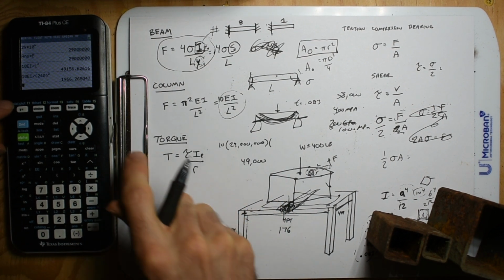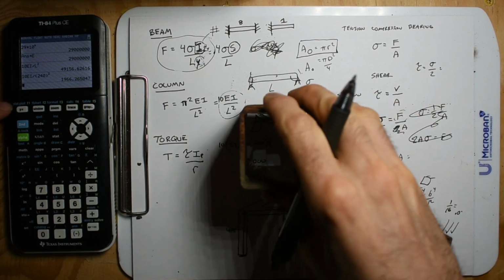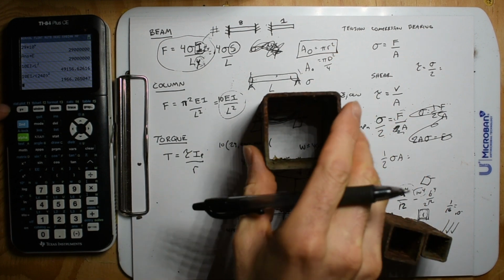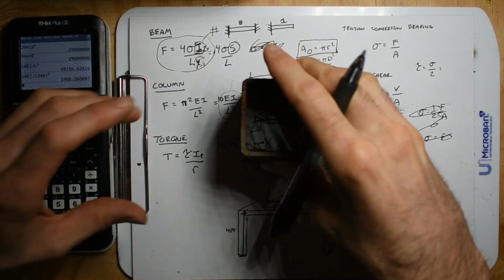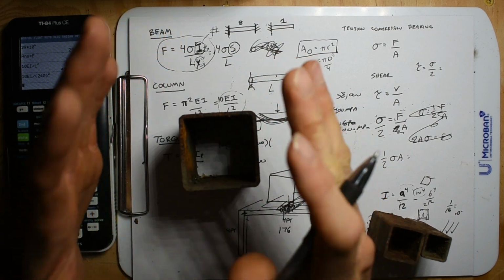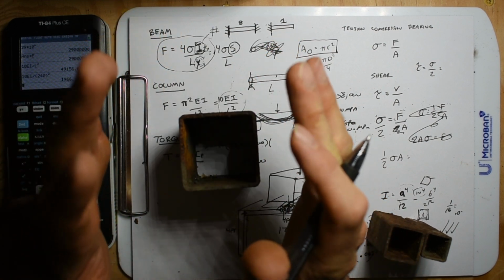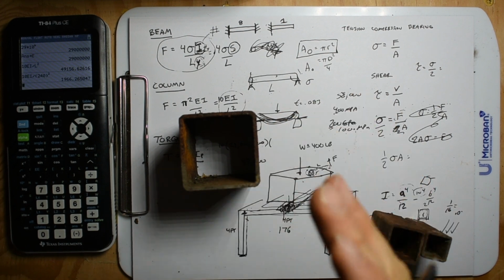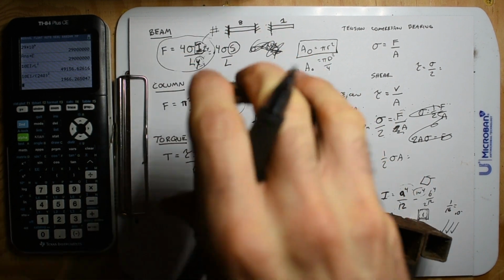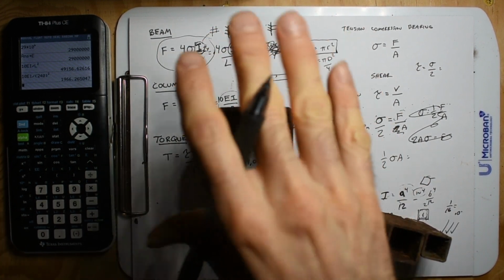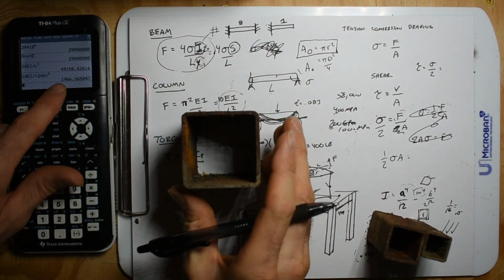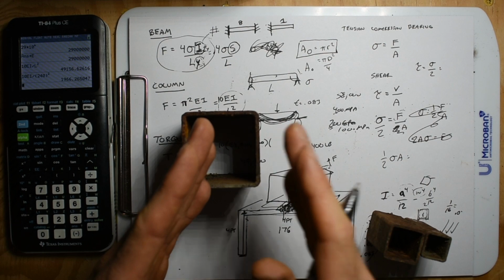So if we could support 20,000 pounds, the thing you're kind of shooting for in comparison is a 2x4. The classic standard of holding up a wall every 16 inches is about 1,000 pounds. You should be able to get about 1,000 pounds out of that 2x4. And so if you put these steel runners, well, you could do them at widths of 32 inches.